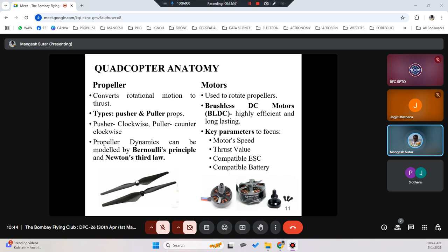So that is how we have seen that the drone is performing more efficiently compared to the straight or plain horizontal motors. Okay, so this new concept has come up. That's why you see a lot of drones designed by DJI where the motors are a little bit tilted. That tilt of 5 degrees gives you better performance than straight motors on the drones.